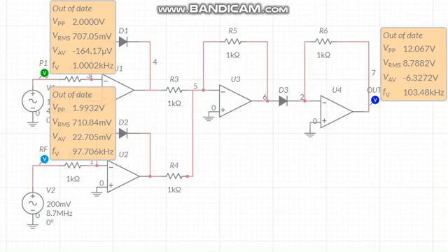If I have to give you an example, the diode has been used here for rectification. This type of circuit, the diode feedback circuit, is used in the multiplier section. Both signals are multiplied at that point, and the output is given to a buffer amplifier. It's not a buffer amplifier actually, it's a voltage following amplifier. Then it goes through the same voltage following amplifier to find the output voltage.